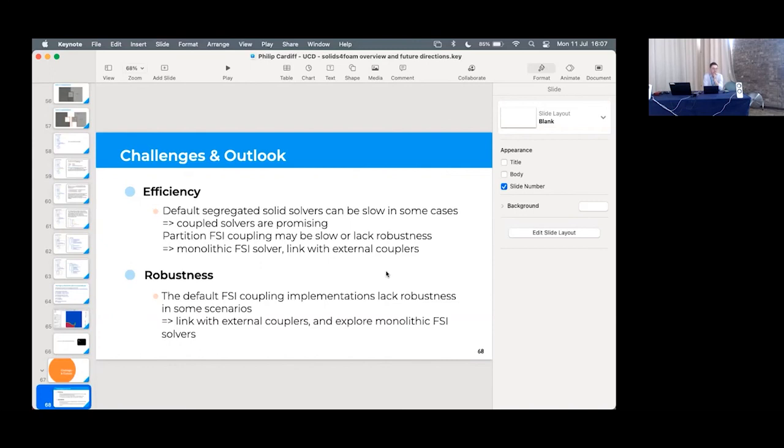Yeah, no, there's no reason you can't do it. It depends. I guess if it's like rhoCentralFoam, then you need the temperature field or enthalpy field or something. You can't ignore that unless you have a really well insulated solid. Well, maybe you can, but yeah, the overall general approach will work.